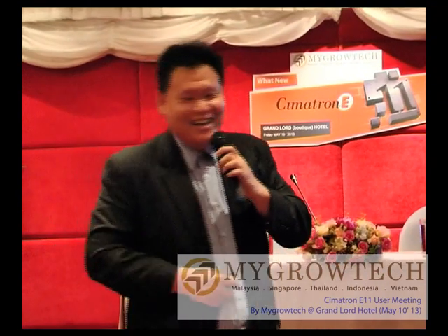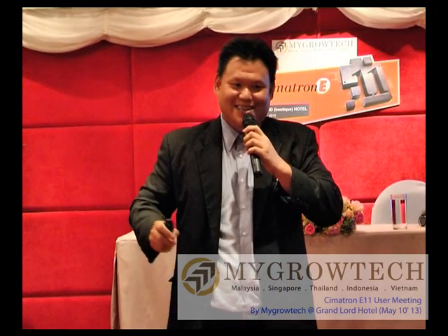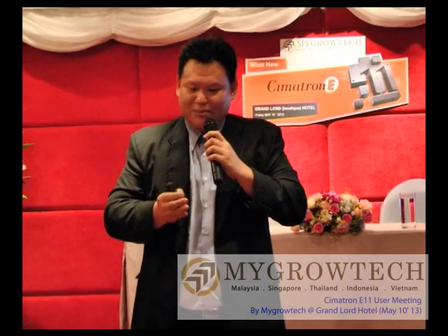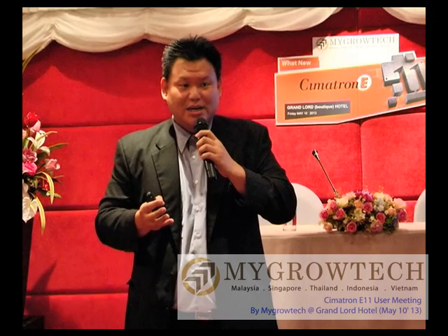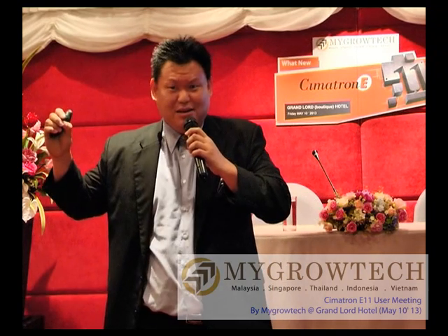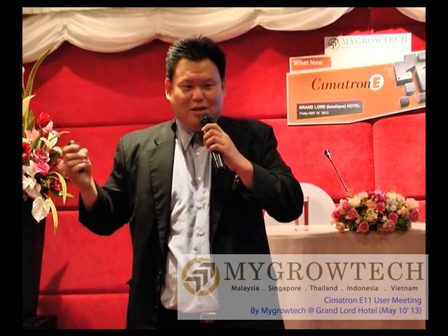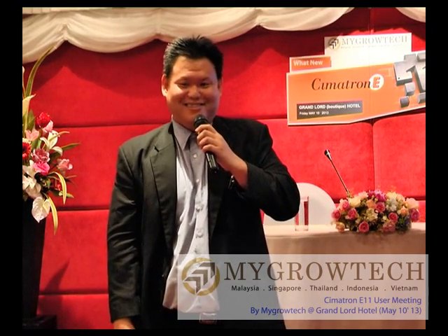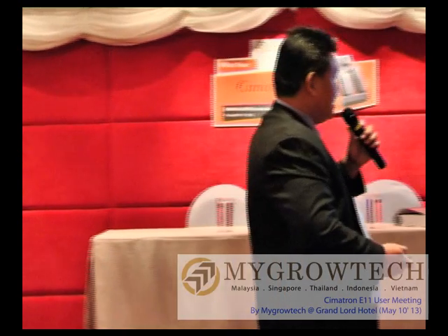And how to increase the chip thickness if I use 10% of the diameter as a side step? Anybody knows? Yes, increase the feed rate. Sorry, I'm out of the dump drive. Oh, you want to take my shirt? Just kidding. Yeah, you should increase the feed rate. This means that if you are using 10% side step to machine the part, you should increase the feed rate, or else your machining is underperforming. Okay, next.